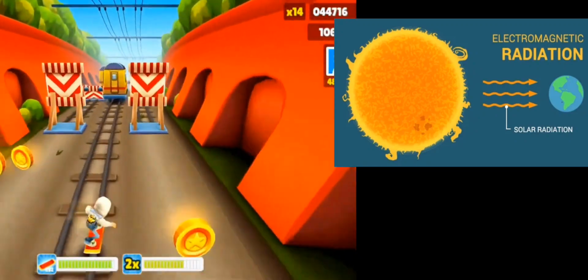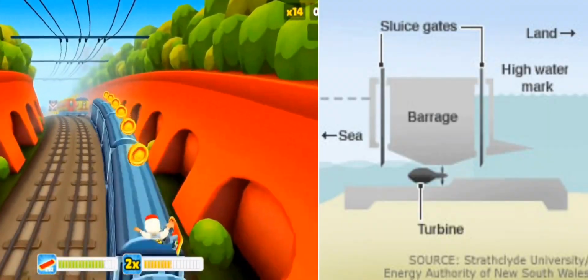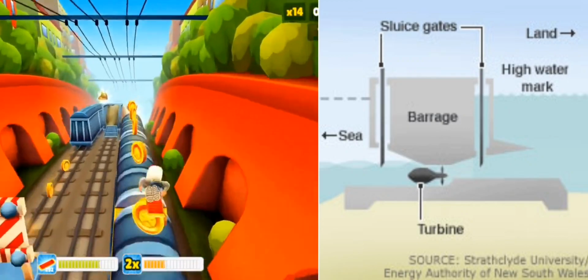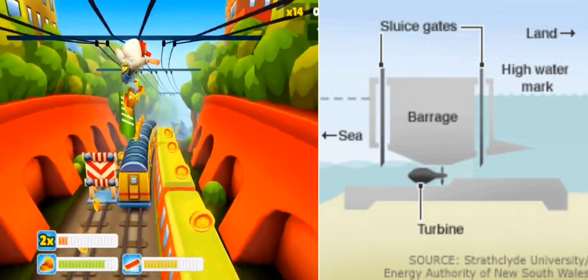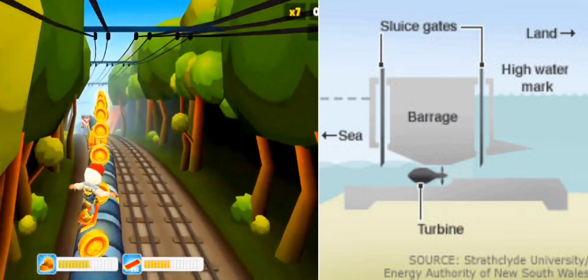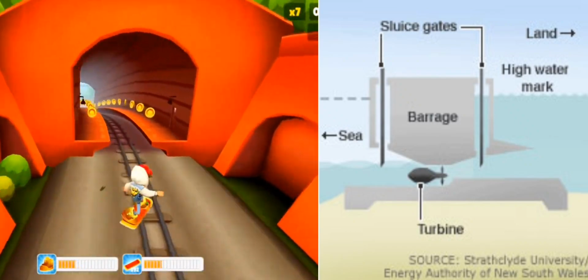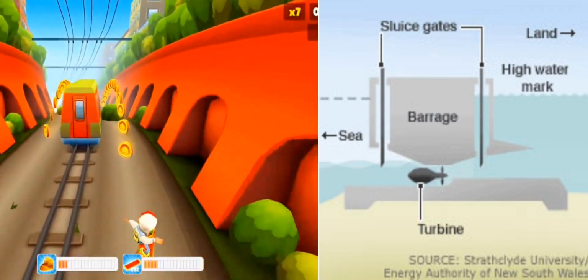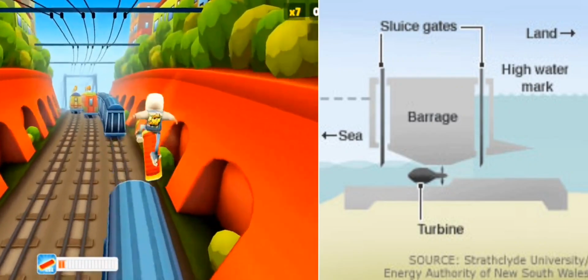Now, onto my energy source of choice, tidal barrages. A tidal barrage is a type of tidal power generation scheme that involves the construction of a fairly low-walled dam that spans across the entrance of a tidal inlet, basin, or estuary, creating a single enclosed tidal reservoir. The barrage has multiple underwater tunnels cut into its width, allowing seawater to flow through them in a controlled way by using sluice gates on their entrance and exit parts.